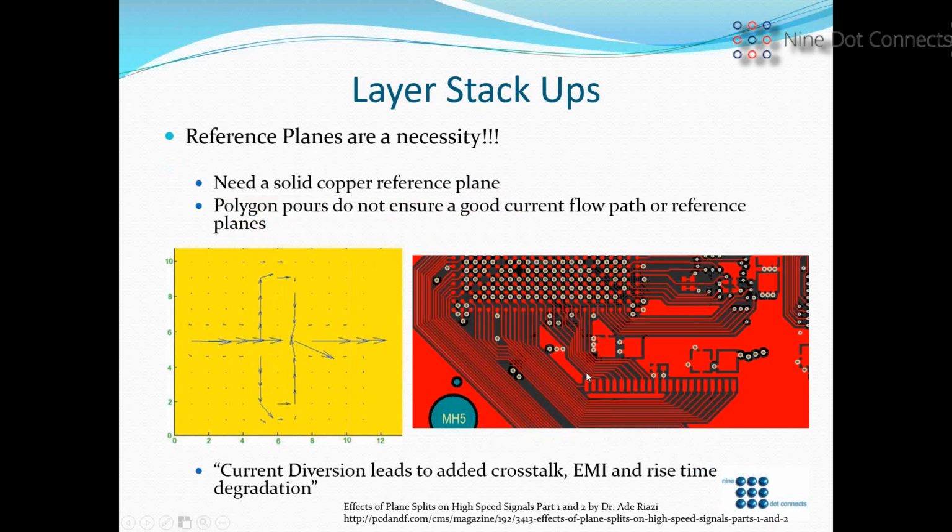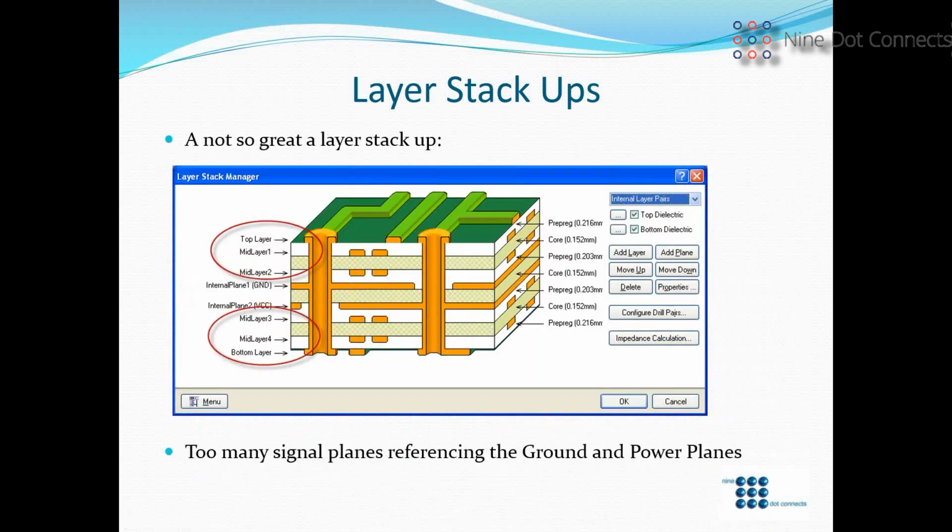There's going to be noise, and you're going to have signal integrity issues because it needs to have that reference plane. So don't use the top polygon, especially if you're using all the copper traces on there, because it's too fragmented. All right. And in fact, if we look at this, here's an example of what a lot of people try to do, and this is not the way to approach this.